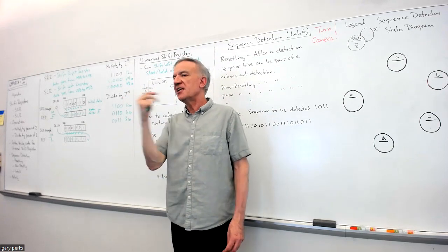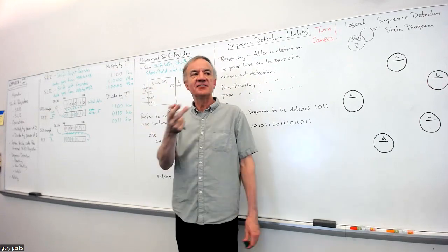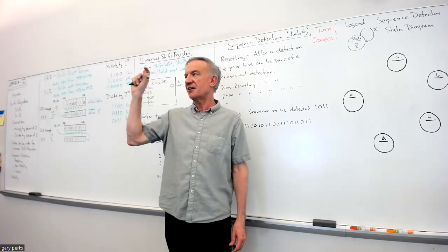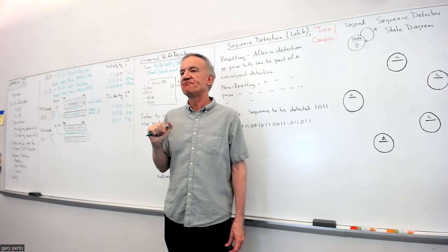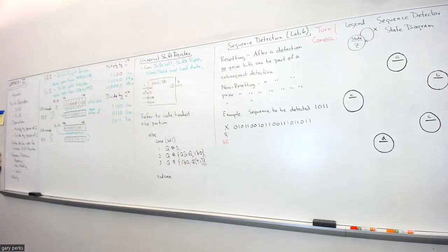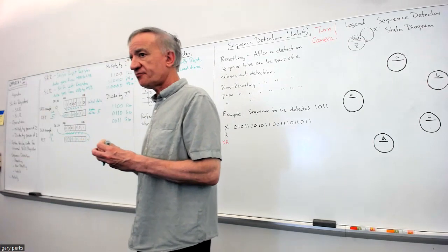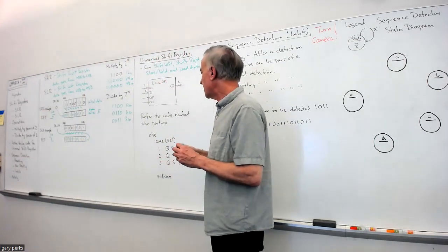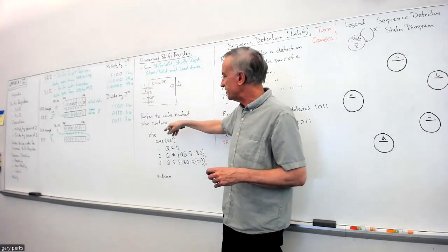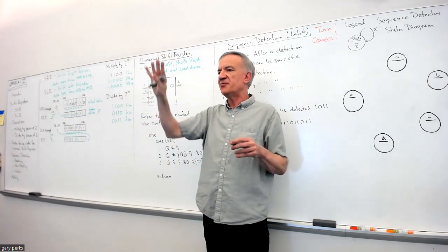So with 2 bits, I can represent how many values? 4 values. Okay, so that select, based on what binary 2 bits are there, is selecting from 4 things, right? Because I can have 0 0, 0 1, 1 0, 1 1. Well, if you look on your table, every table should have a handout that has SystemVerilog code for a shift register like this. I didn't write all the code on that handout, because what's at the top is code we've already talked about before, so it should be familiar to you.